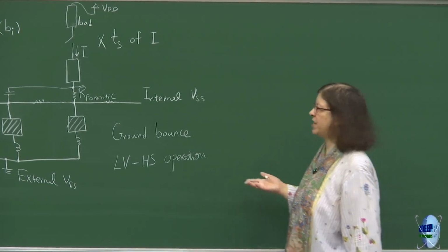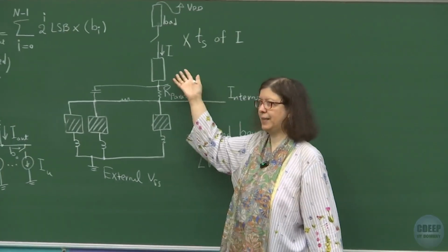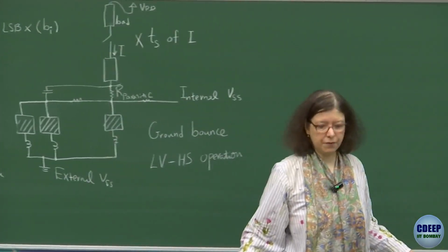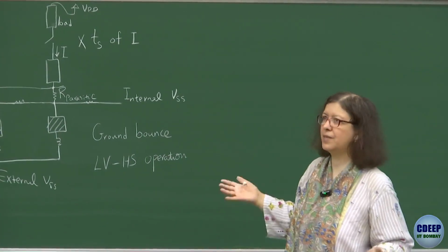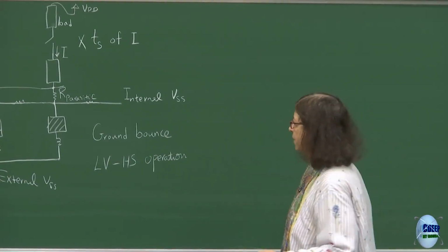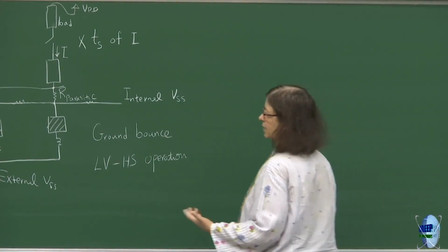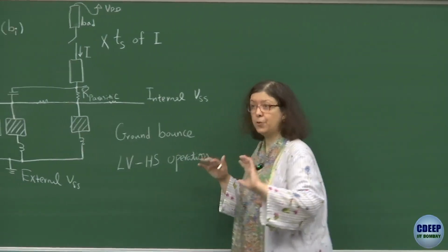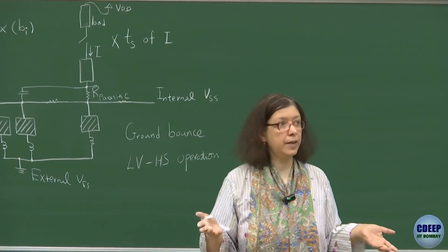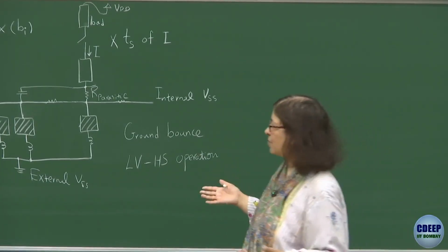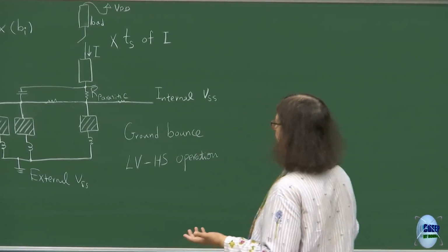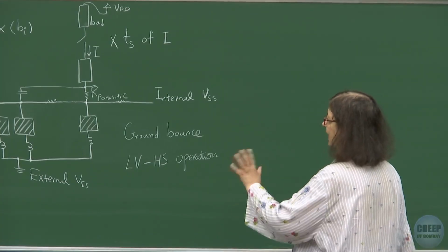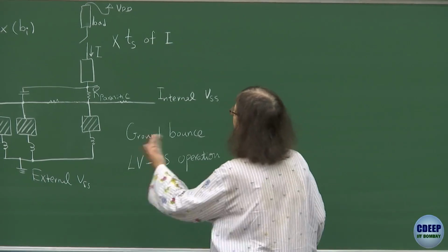Anyway, we are switching them at high speed, which means dynamic power is already high. So there is no point worrying about static power. Therefore, the better technique that comes to the rescue is to use differential architectures. Not only do we get better swing, but with a similar current we are also able to get a constant current drawn from the supply.